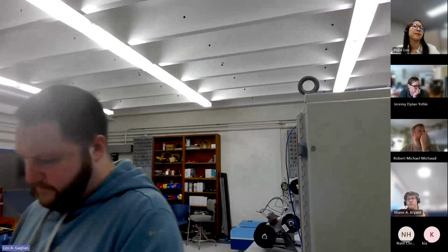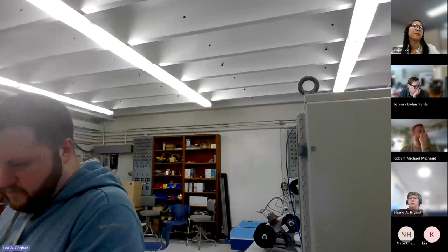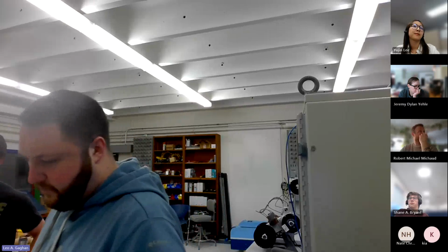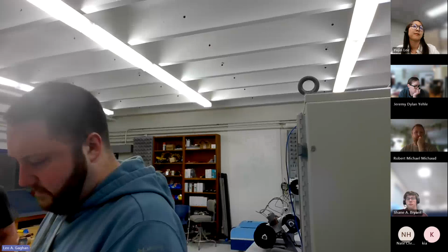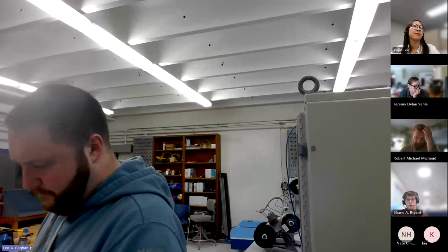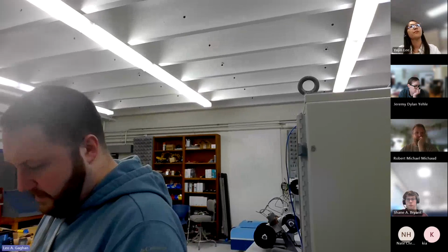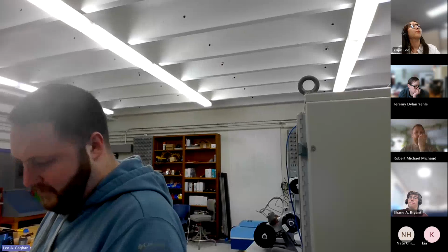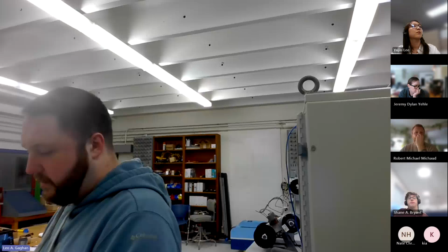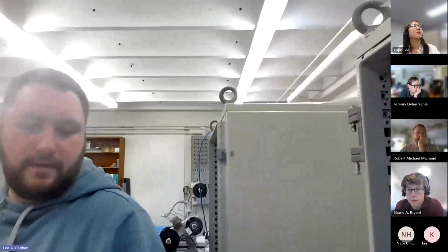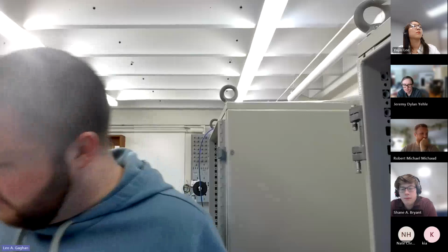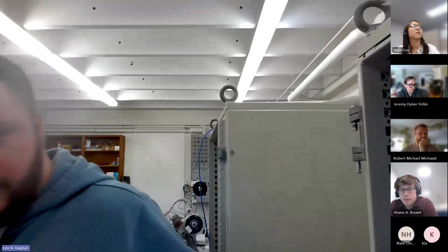So let's say I come in. You guys can see if you go to sheet 3, we've got our reclosing logic. And if we have a trip, that'll do our reclose initiate. So I've got to make sure I've got 79 on. I've got my 79 fail. I think that'll drive the reclosing to lockout.